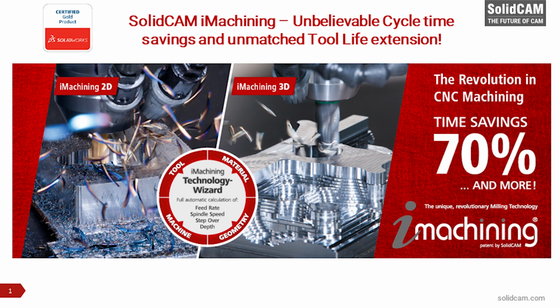With iMachining, because we're maintaining that constant chip load and we're minimizing any linear or lateral load force on the tool, it's only seeing really rotary torsional force. Those smaller tools will last significantly longer.